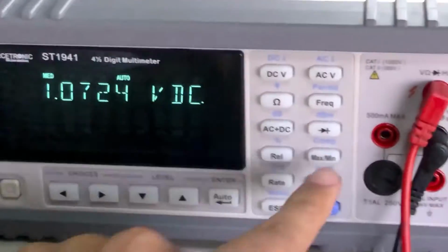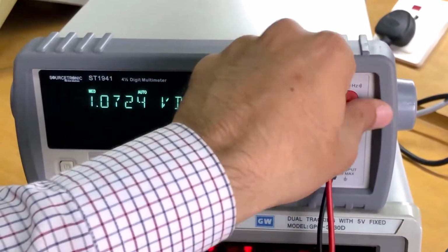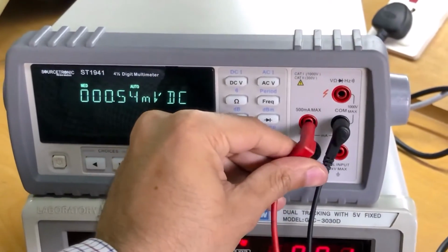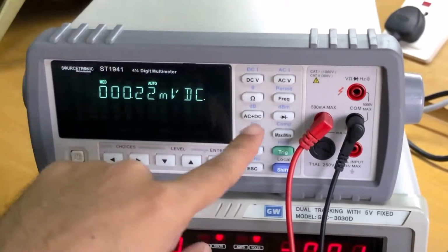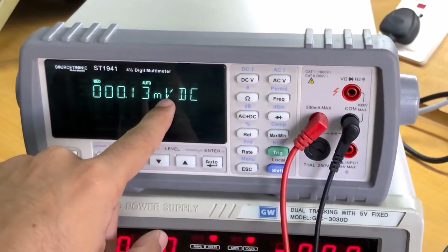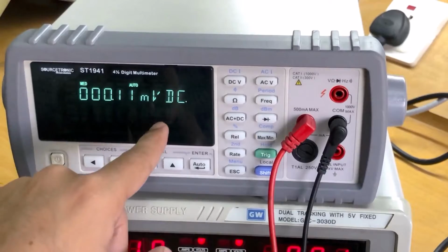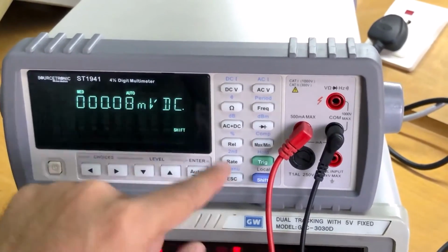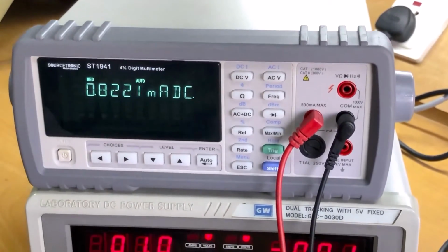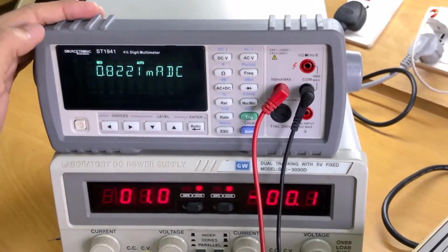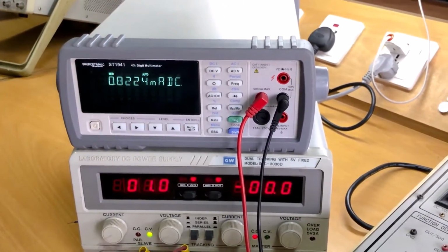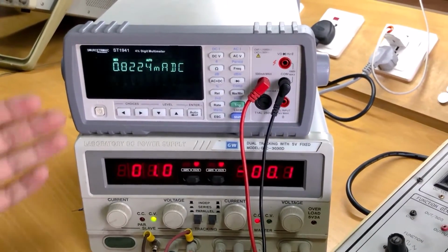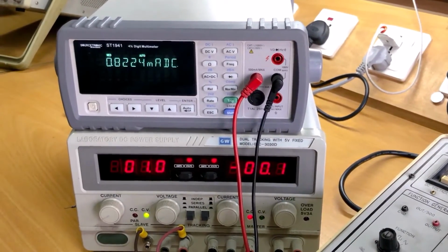I have to remove this probe from the voltage probe to the current probe, and then it is here showing you the value of VDC. First of all, I have to change this to DC current. I will press the shift button, and then I will have to press this, and the current flowing through our circuit is around 0.822 milliampere, and this is the DC input, so your current flowing through the circuit is DC.